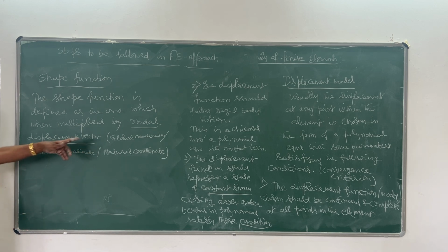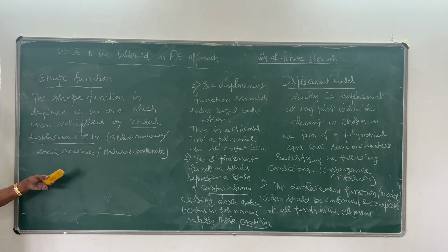After defining this, you have to show the components of this displacement, because displacement is a vector quantity, so you should have direction. You are choosing the direction in any one of these ways. Out of this, you have to choose the nodal displacement, which is what we have to determine during analysis.